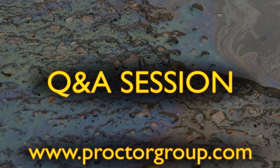Okay. Another question via email, how can I tell a hydrocarbon membrane from a non-hydrocarbon membrane? Yeah, again, there's a lot of membranes on the market that claim hydrocarbon resistance, but I suppose the only really way to find out how good that membrane is, is to ensure that it's been tested against the suite of chemicals that are in 748. If you do that, you then know at least you've got a comparable membrane against a whole range of different hydrocarbons.